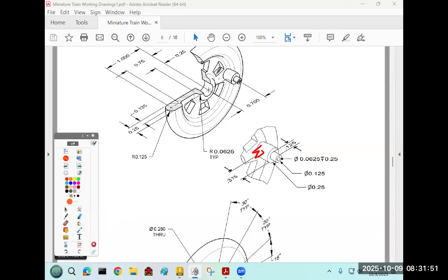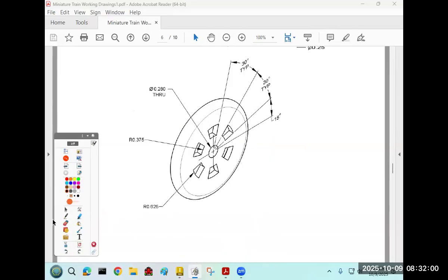We want the linkage nub to end up on a spoke rather than on a hole. And that's why we need to do that little bit of offset. So we're going to start out with 3 lines. One that snaps to horizontal, another line that is 15 degrees off of that, and another line that's 30 degrees off of that, from the center on, and we're going to do the sketch.